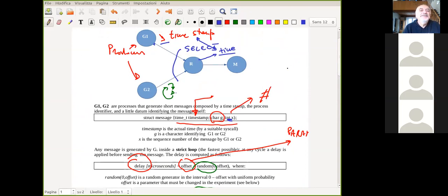And generally, you decide to buy a processor or a hardware system because your control system for moving your arm or your mobile robot needs such exchange of data between the modules in the architecture. Remember the scheme of the mobile robot. So this is a problem that is related to many automation systems, real-time, not strict real-time, and robotics in particular.